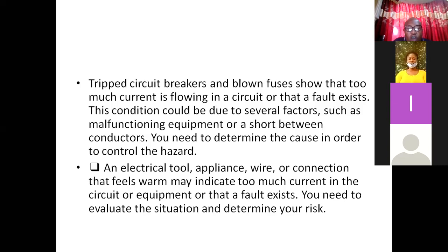So you must always check it. You need to determine why a fuse is cutting all the time, or why a circuit breaker is tripping all the time. Also, check an electrical tool, appliance or wire that feels warm. When you touch a wire and it feels warm and it's becoming hot, some people just say, "That wire is just hot." No. An electrical wire should not just be hot anyhow.